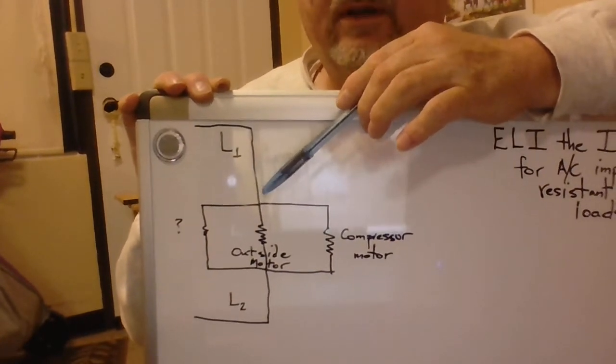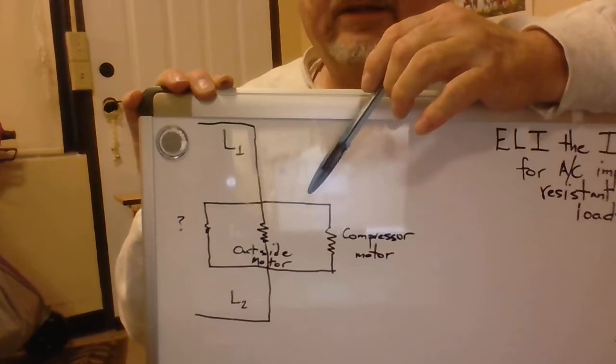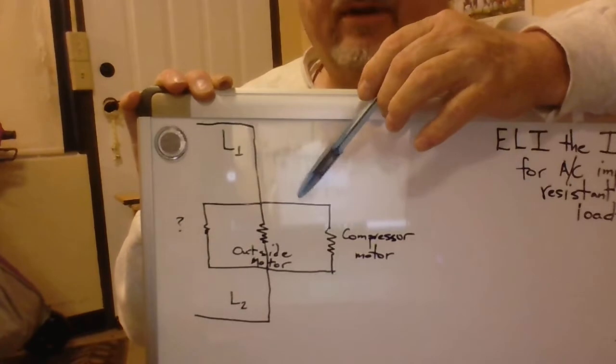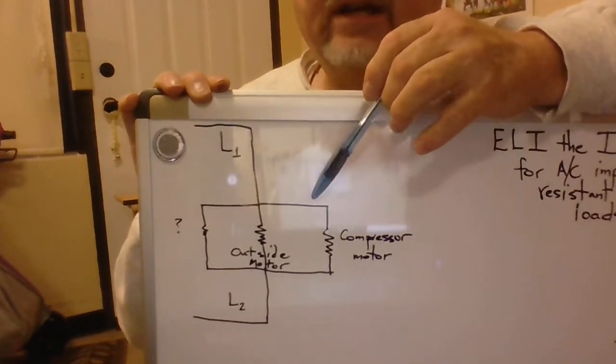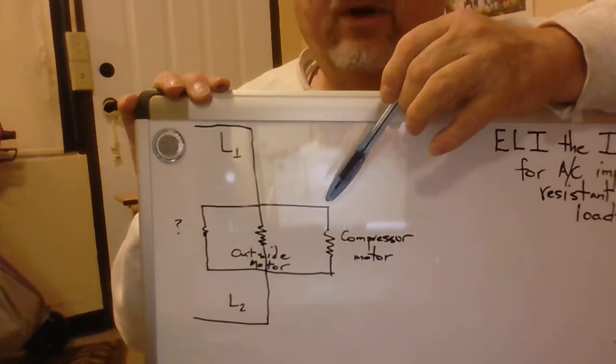It will cause the compressor to fail at some point. It was just lucky the customer had established that the fan wasn't running separate of the compressor when we initially talked, and unfortunately I just didn't know what size motor to bring with me.